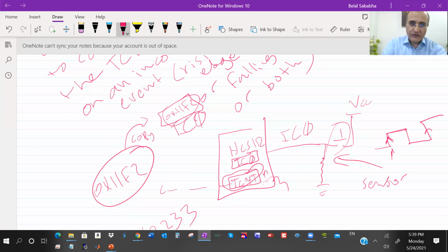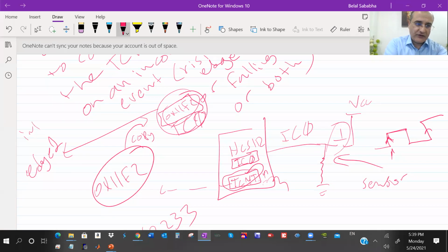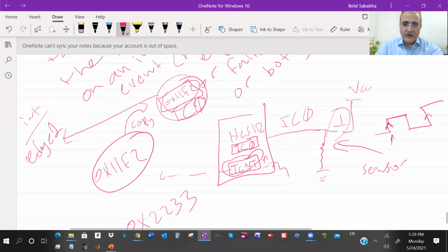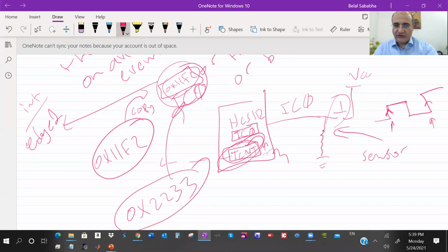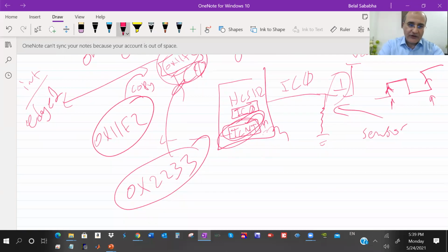You can save this value somewhere and store it in something called edge 1, an unsigned integer. Then on another rising edge, this is going to keep running. It will be captured. You will be interrupted or notified through a flag or whatever. You can take this value and store it at edge 2.